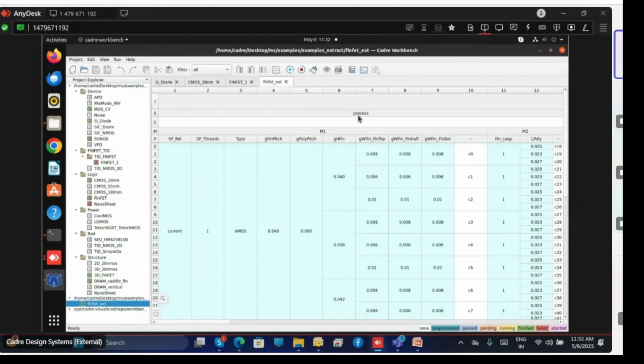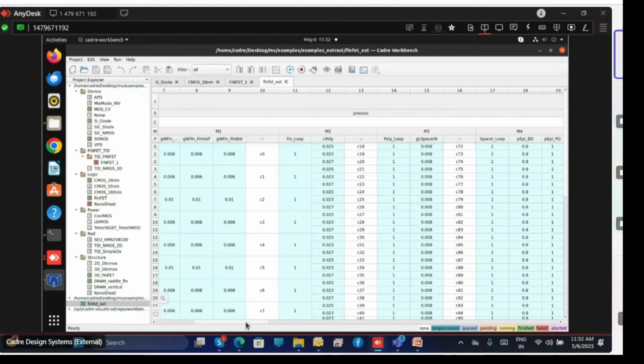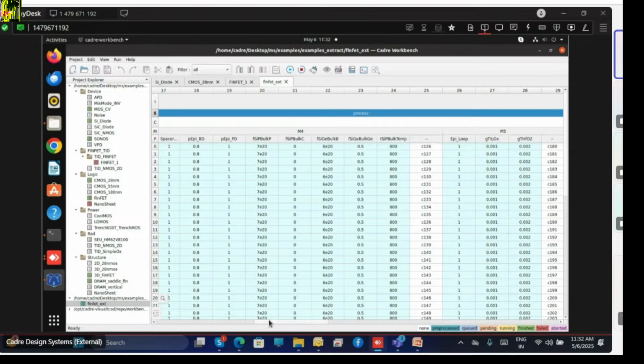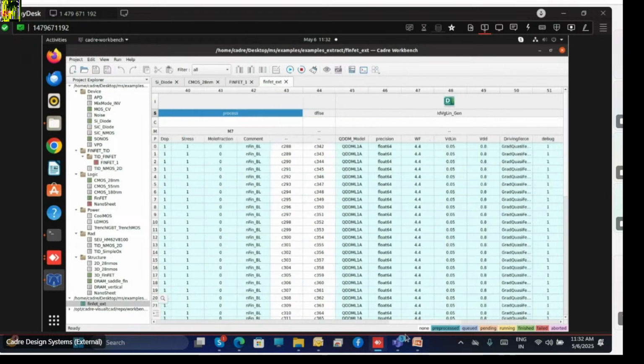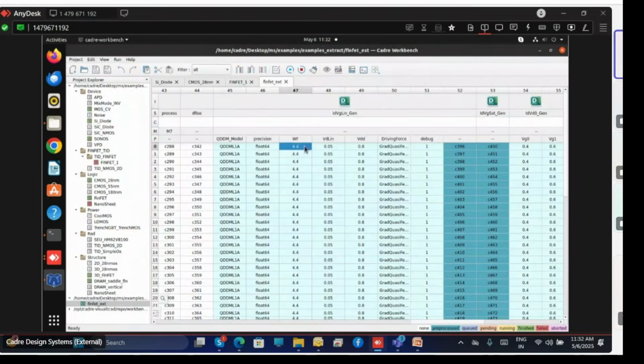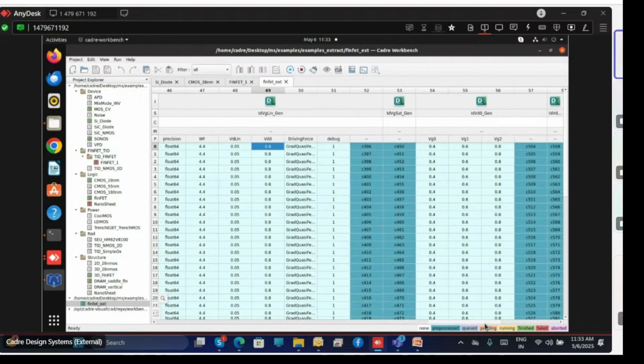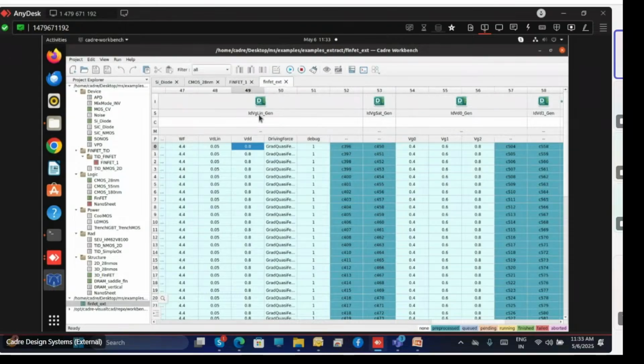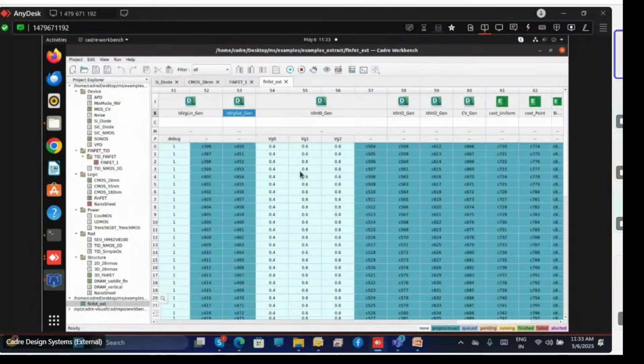This is a FinFET process example. In this, we have written a FinFET process script, then a FinFET device script. We are using work function 4.4, linear at 50 millivolt, saturation voltage 0.8 volt. Then we are doing an ID-VG simulation, linear and saturation. Then ID-VD simulation at 3 different gate voltages, 0.4, 0.6 and 0.8.